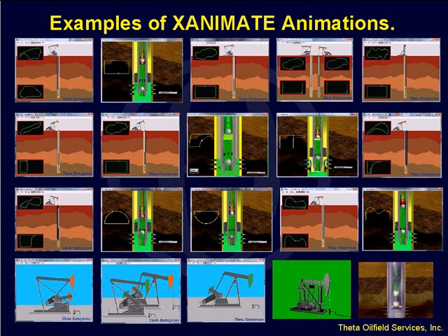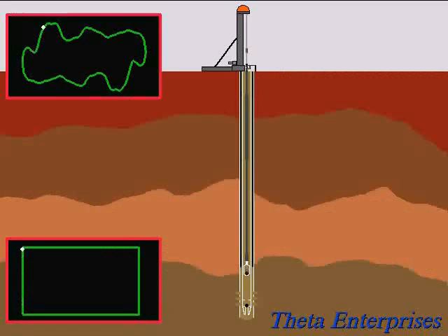We also have animations for different kinds of pumping units, like the Rotaflex. This is a Rotaflex animation with steel rods. As you can see, the delay between what happens at the surface and what happens at the pump is not as big because even though the steel rods stretch, they don't stretch as much as fiberglass rods. And also notice the movement of the plunger. It's not moving in a smooth manner. It moves, pauses a little bit, or slows down a little bit, then moves again. And that has to do with the waves that are moving up and down through the rod string.